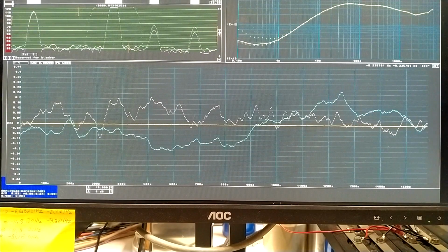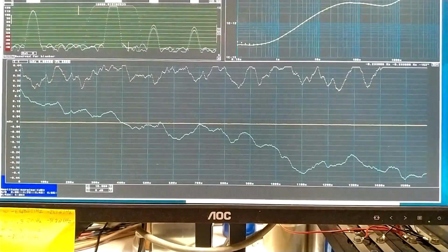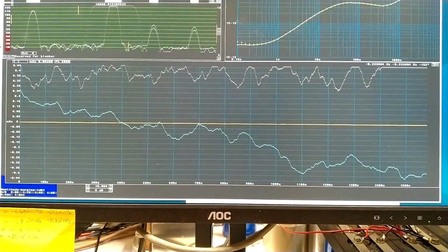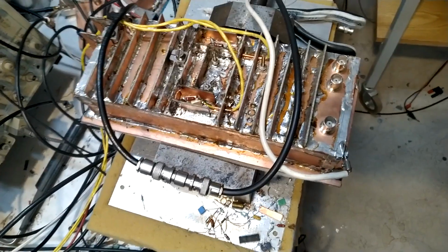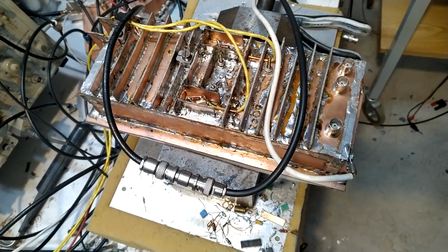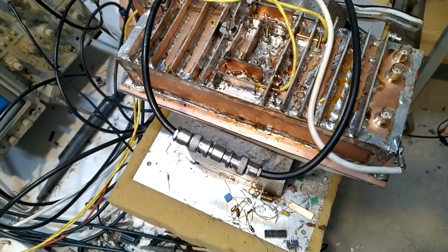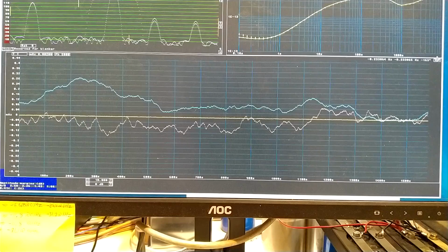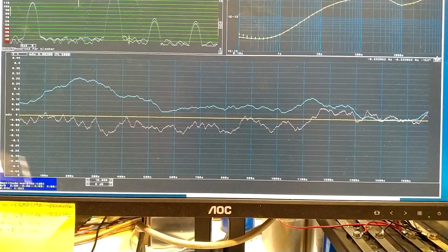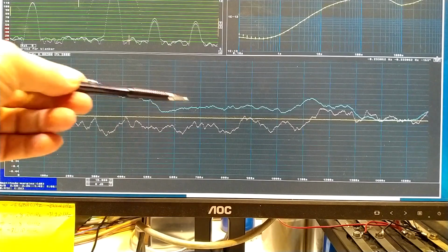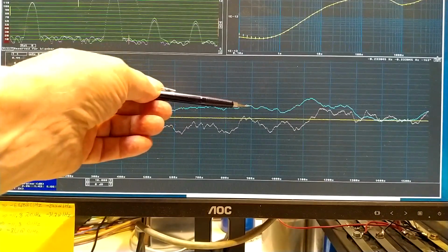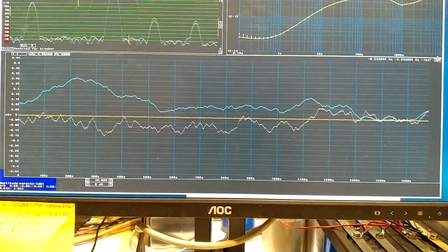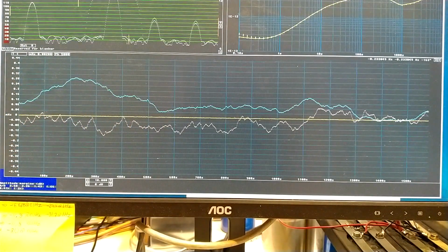And here is the old result at the higher power level. And it's not really perfectly clear, but I have a feeling this is something that has some meaning. I have disconnected the selective amplifier and replaced it with a BNC female to female adapter. The phase variations, the blue trace, do not have so high amplitude in these fairly high frequency variations as they had before.